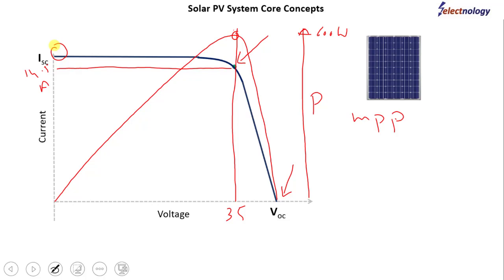So the PV module shall be operating at the MPP, the maximum power point, and the inverter which has this feature has a particular algorithm or device inside it, which is called MPPT, maximum power point tracking, meaning it is always running an algorithm inside the inverter to operate the PV module at this point to maximize the power supply.